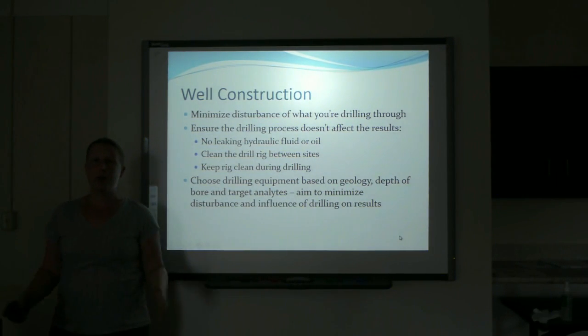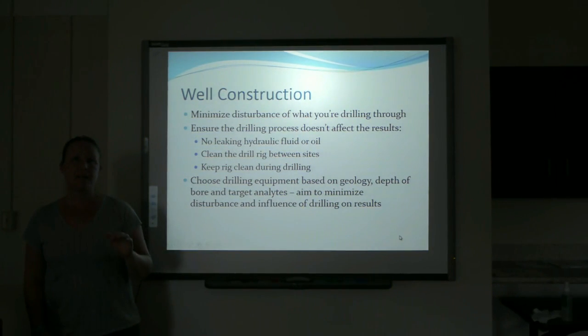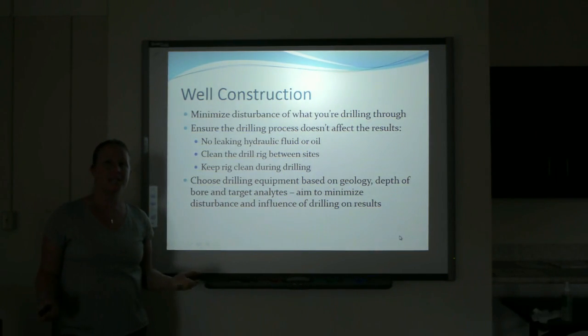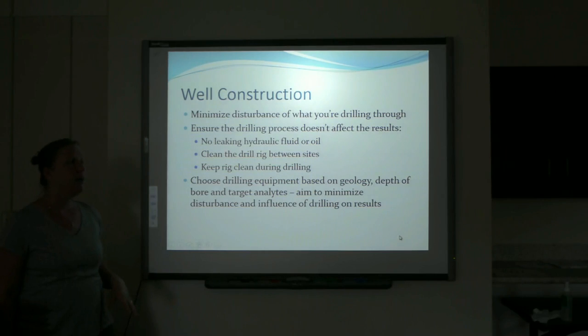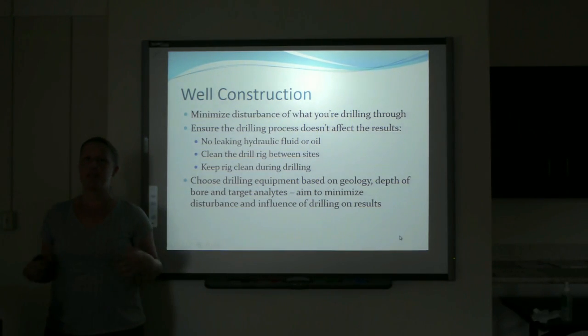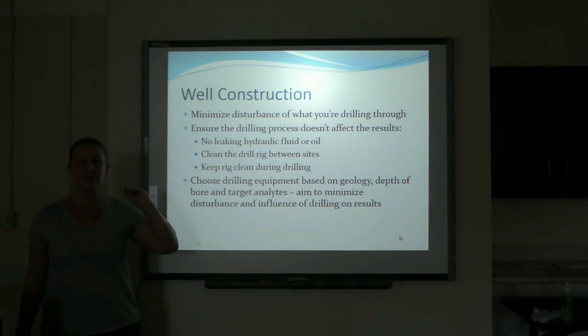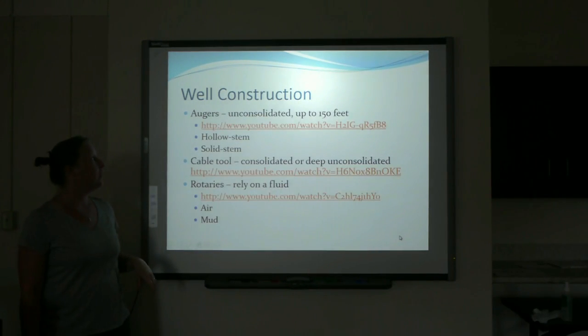So it's really important when drilling to not have the drilling mechanisms affect your results. So avoiding leaking oil, cleaning the drill rig between sites, and keeping the drill rig clean while you're at site will help minimize contamination of your wellbore. And then choosing the right drilling equipment based on the geology, the depth, and the target analytes. Really, you're trying to aim to minimize disturbance of the drilling method on your results.